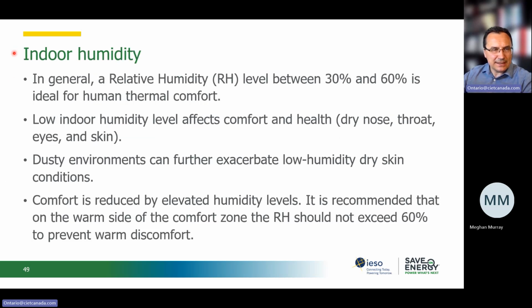Indoor humidity is another element that defines thermal comfort. And when we refer to indoor humidity, we are working with relative humidity. In most of our buildings, a range of 30 to 60% is associated with the perception of thermal comfort.